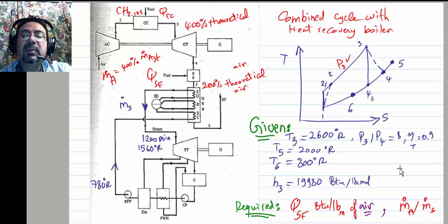H5. CpT, right? Yes. If you assume Cp and you know the temperature, you can get away with this in the exam, CpT. But to make it more accurate and more complicated in this example, he is actually using tables for air. There are tables. So ideal gas, yes, CpT, perfect. But there are tables that account for the variation of Cp with temperature. Not just the variation of Cp with temperature, but the variation of Cp with composition.